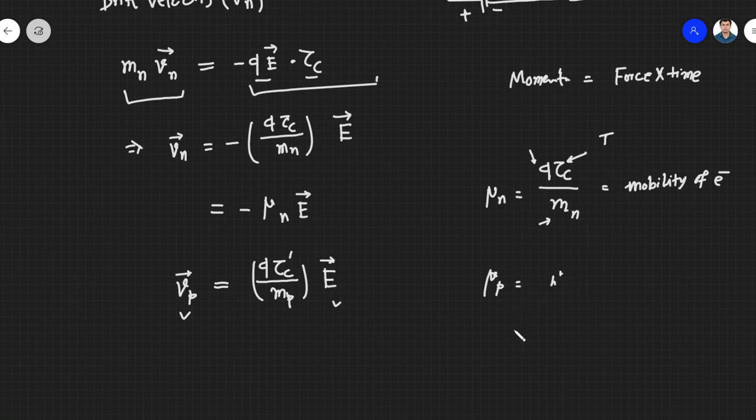Now when it comes to the conduction phenomenon, the electrons and holes cannot simply move freely in the lattice, right? When they try to move, they will see different scattering phenomena. Why? Because in the material there are different potentials, since in a real semiconductor we will be doping with some impurity atoms, let's say aluminum or phosphorus.